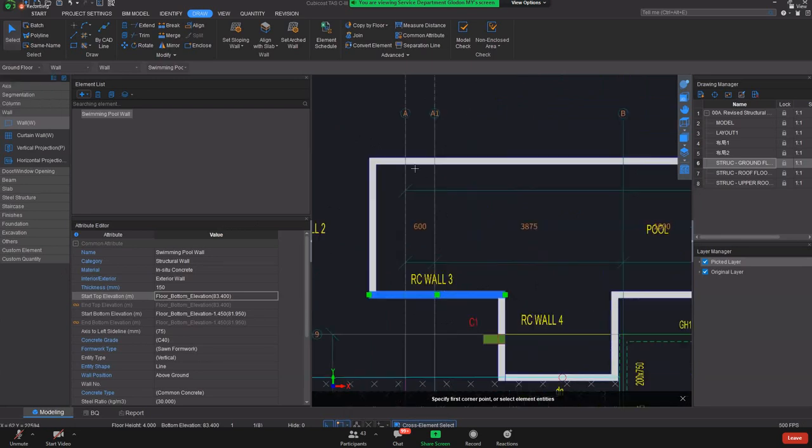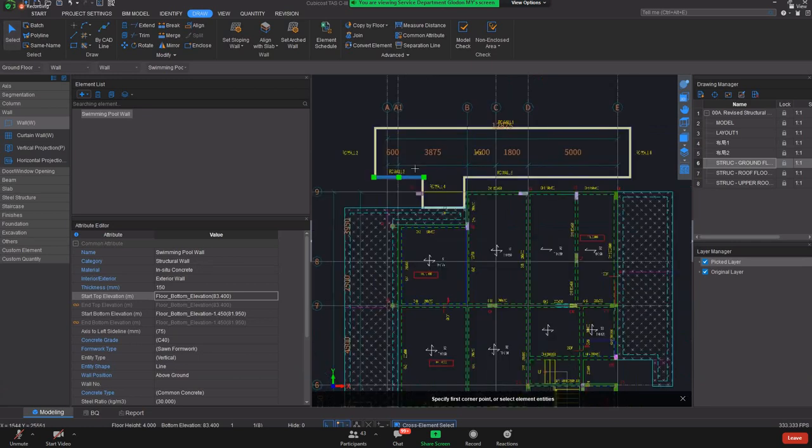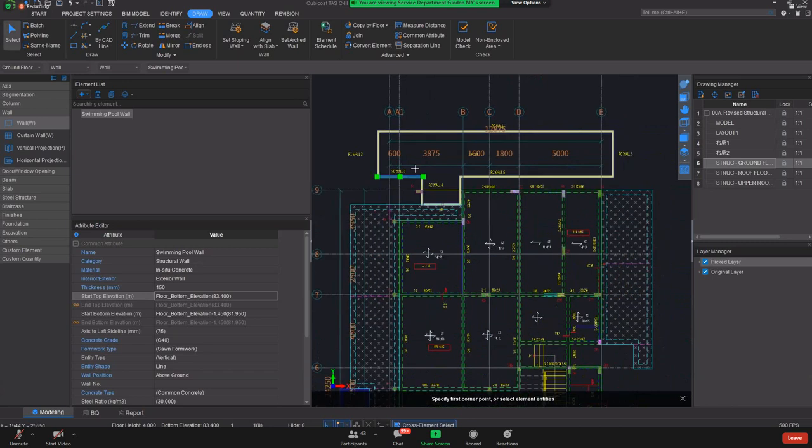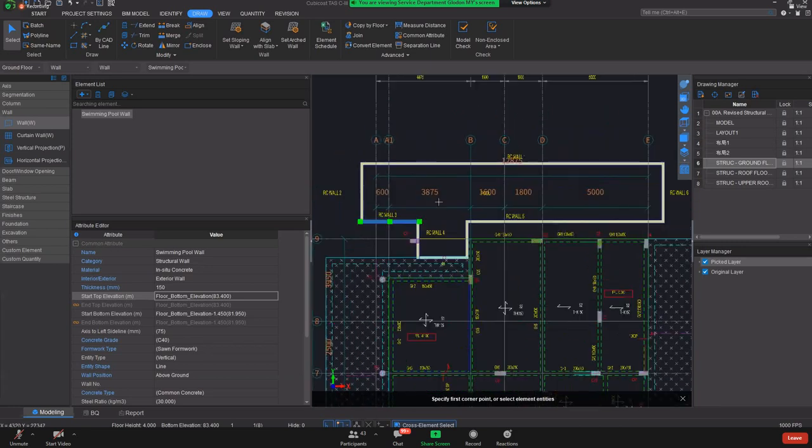In fact, you also cannot do so because we don't have the drawing. We don't have the indication line for the foundation layouts that have the swimming pool. It actually depends. If the CAD line shows at your first ground floor, you can put it in the ground floor. If you want to put it in the foundation floor, you also can, but the concept will be slightly different. You need to add instead of minus the bottom elevation.